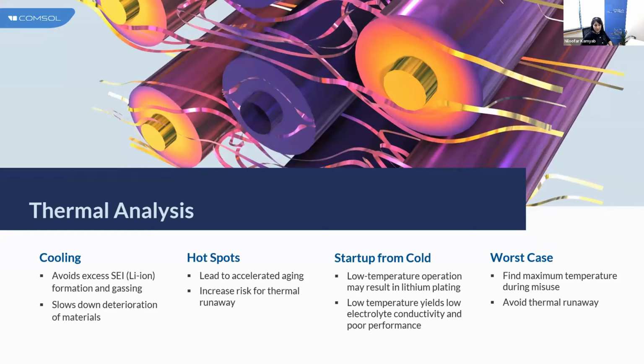And then we already know what happens. The temperature spirals out of control and the cell starts destroying itself and leads to many catastrophic consequences that we want to avoid for obvious reasons. And again, if you have a battery pack, you have bigger issues, because the thermal runaway doesn't stop with a single cell, it propagates throughout the entire battery pack.